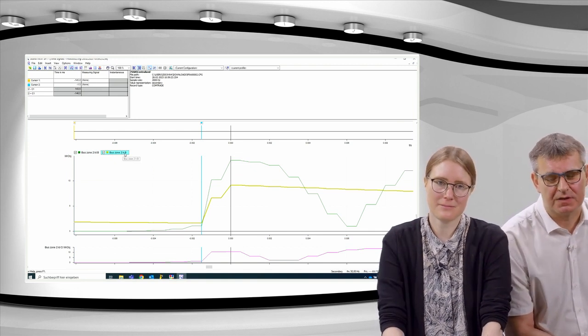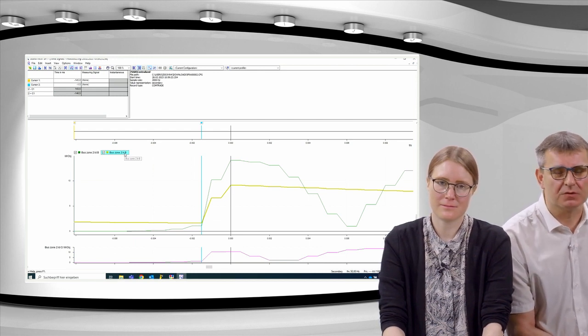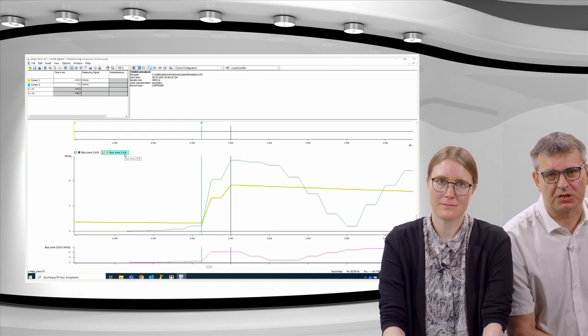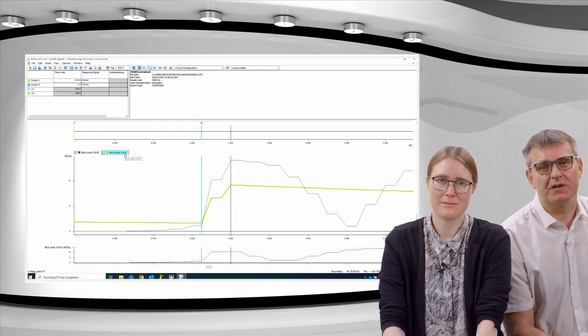If you remember, I have explained we are not working with the calculated restraint current. The algorithm is every time working with the so-called modified stabilization current. The modified stabilization current is the same as the calculated stabilization current